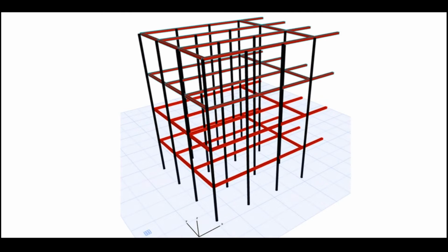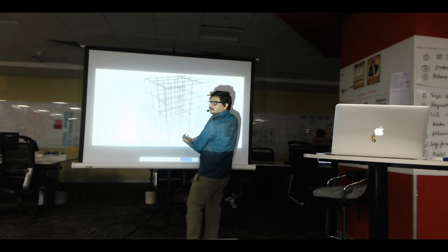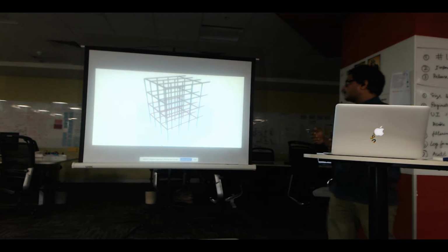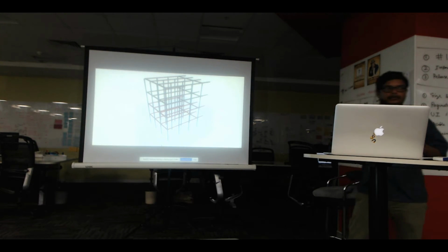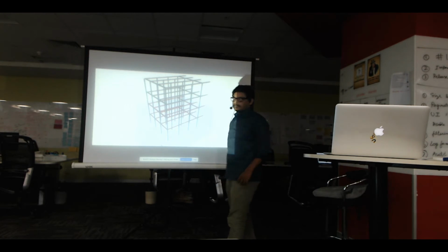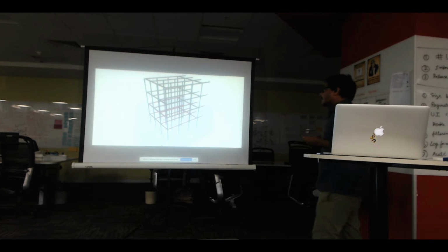And if you have to get all the LEDs in this layer to light up, give the signals to all these columns and the layer that you have chosen. So by this we have really reduced the number of pins that you need to control the LEDs, and do it quickly so you create the image. And that's how we have solved the problem also in the previous video that I showed.